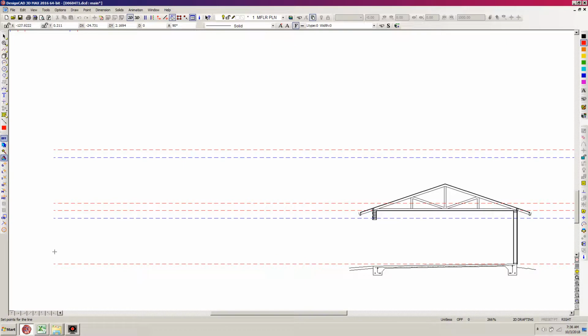So what we have here is I'm going to right click here and go up to our finished floor line, and I'm going to be looking at the DY dimension, gravity move, and I'm at 9.1458, and I'm going to add a foot to that. So that's going to be 10.1458 feet that we will be going from the top of the concrete landing to the upper finished floor level. Again, that's 10.1458.